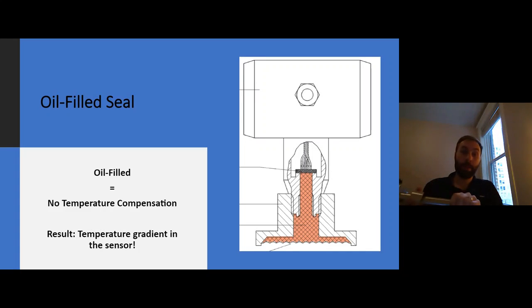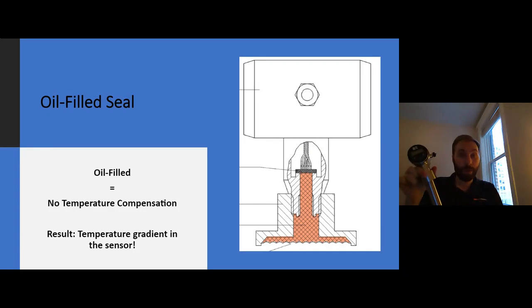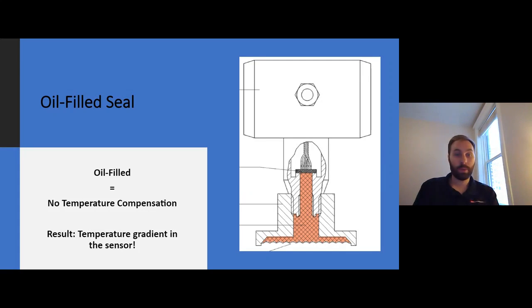I also want to point out that this can be worse with the dairy sensor, with how long this is. There are some manufacturers that put a bunch of fill fluid all the way up in there. We do not. We use the flush diaphragm technology in this as well. So you can see how the temperature problems might occur, and you can see how you don't know what's going wrong until something goes wrong. And this might be one reason why.